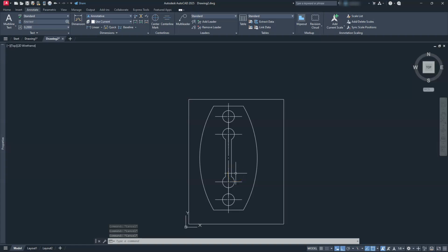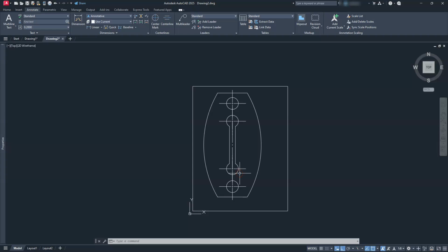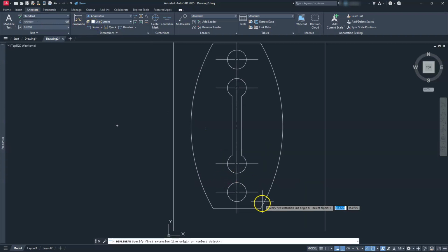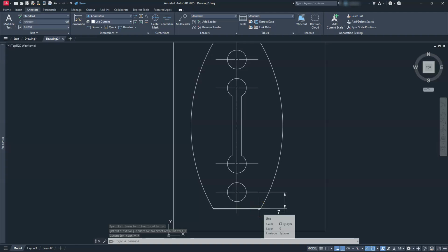Okay. All right. Now we're ready to put the dimensions on. Now, I would normally make layers and things of that nature, but I'm just kind of giving you a quick overview on this one. And it should be super simple and easy enough to do or see. All right, let's go ahead and put some linear dimensions on here. So I'm going to go here first. I'll put a dimension from this endpoint to here. Come down this way. Now, I hope you notice why I selected it that way. I selected this one first to this one. And remember that it flips to the last side that you select. So that was the last endpoint that I selected. So therefore, my text is going to be on that side.